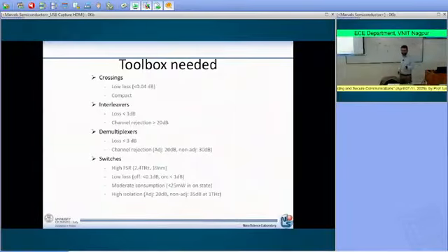The demultiplexer should be able to separate the single input waveguide where we have the 12 wavelengths into 12 different waveguides. Okay, so we demultiplex the signal from one waveguide to 12 waveguides. And this demultiplexing is based on the wavelength of the light. So lambda 1 should go to the first waveguide and lambda 12 to the last waveguide.